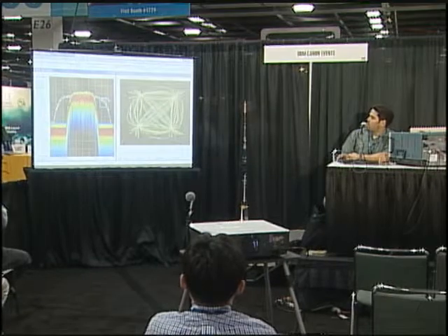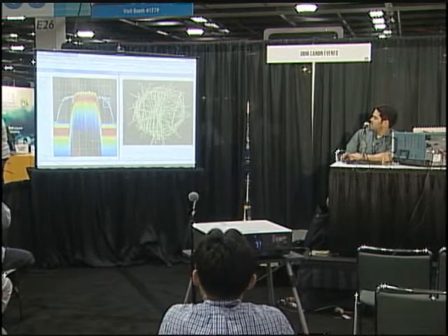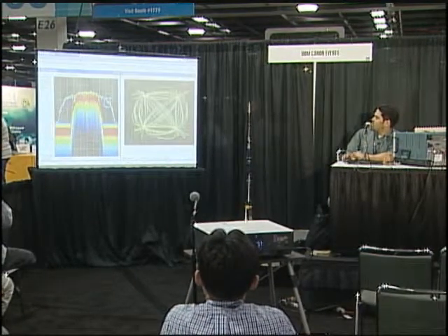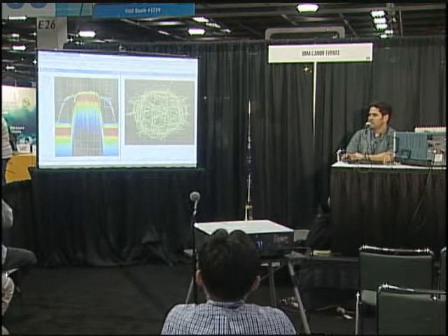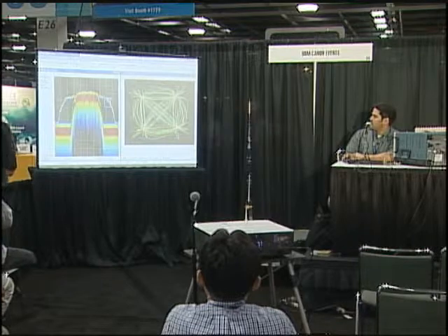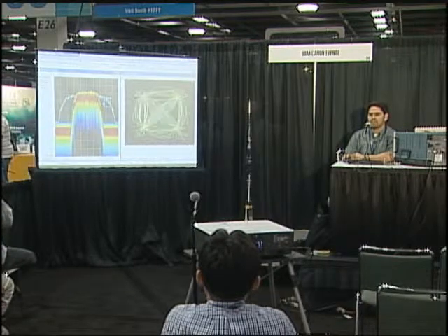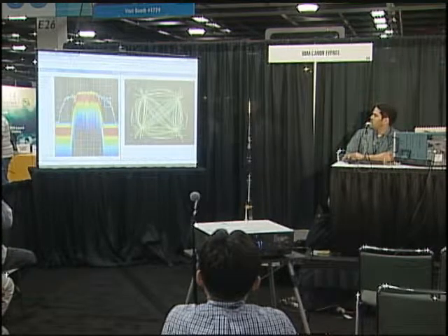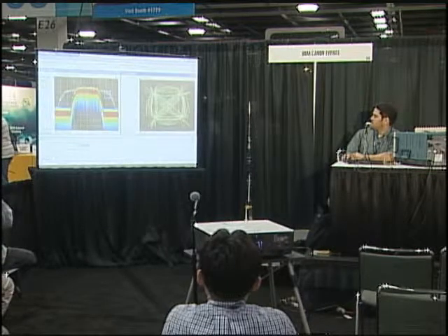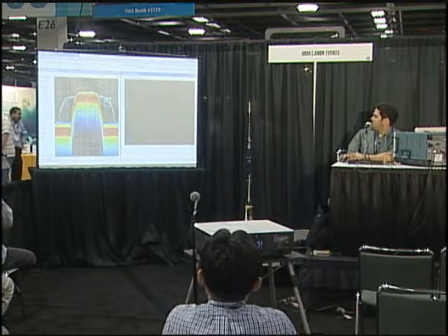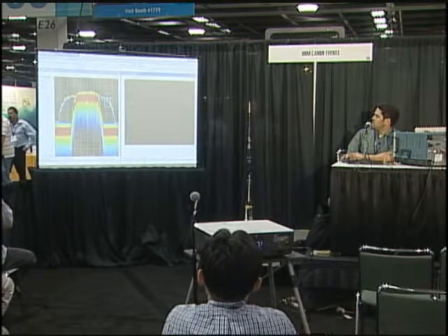I put the trigger on this mark here, and I'll see how the Constellation looks. So we are synchronizing the acquisition over which the Constellation is calculated with the appearance of these shoulders. So we can also look at the Constellation this way. Just look at the points and see how they're all over the place.